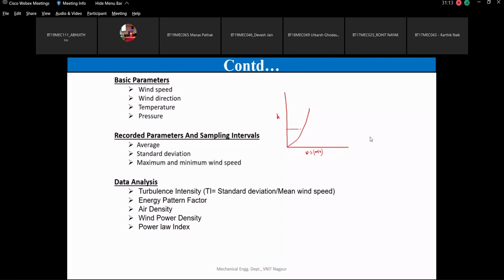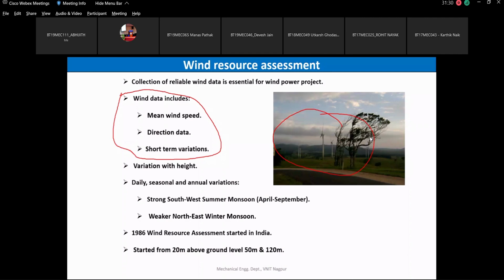Before that, we have to collect the wind speeds and the related data, including the pressure, temperature, humidity, and solar radiation, everything we must calculate, and the wind speed at different heights. And if the wind speed is that much, like 20 meters per second, for how long may it continue? It is not like for the entire year we'll get 20 meters per second wind speed.